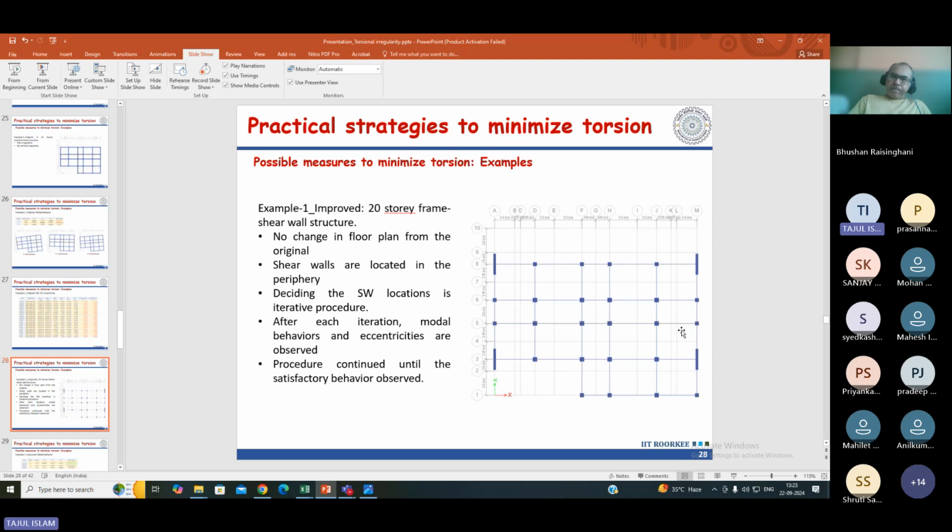how much will it affect the structure? It will affect, as I told, depending on sizes and how much offset you are giving. As you said, it has a 1 meter dimension in one direction. So you are connecting at the center in your model, but connecting at the edge in your actual construction. So there will be an offset of around 400 to 500 mm. That is significant. So why go for center to center? In software the option is available, you go for offset modeling instead of center to center. Yeah, but offset modeling takes too much time.